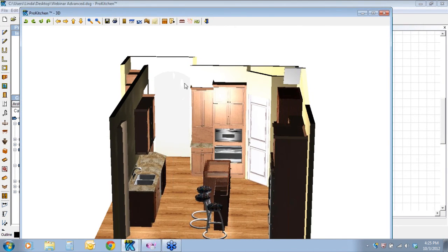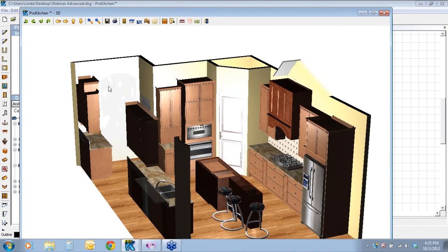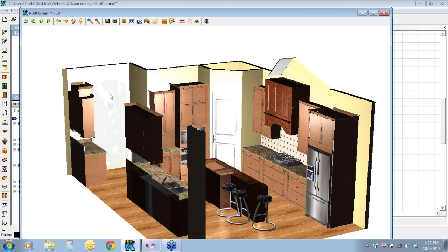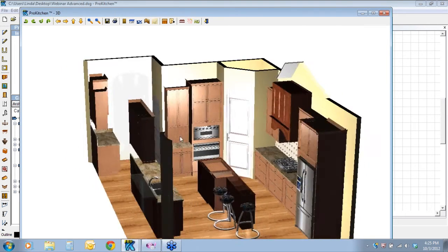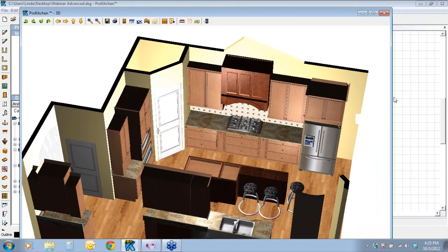And you can see here, when I move around here, I've got this little archway right here. I've set that to invisible. That's a user shape with it to portray an archway opening through there. And I've just got it like an invisible transparency on it. Okay, so that's how you get your vaulted ceilings in there.